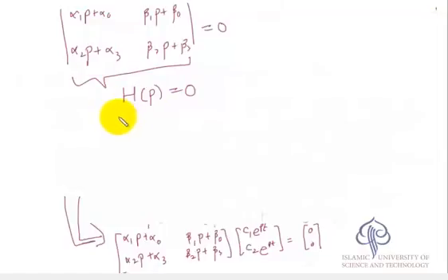The determinant equal to 0 is the characteristic equation for the set of simultaneous differential equations. It will be a quadratic equation because you're getting powers of p, so power 1 of p and power 1 of p are getting multiplied. Okay, quadratic equation, so you'll have two roots, p is equal to p1 and p2, and then you can put in these two roots in the solution that you have assumed to give you the two variables.